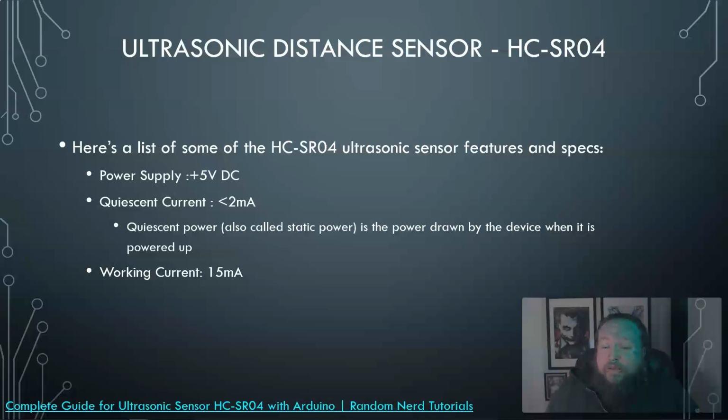But we know this ultrasonic is going to take that. So if we threw in 2 ultrasonics, if we're even able to connect that to our controller and use that, that's going to be a total of roughly 15 milliamps drawing, and that's more power consumption. Even just having 2 sensors, throw in some actual effectors and actuators there, it's going to draw more power and could cause issues. You're up to that max of how much power the Arduino can provide. And if it's plugged in by USB, well, you've got limits. If this is by battery, that's also going to affect how long the battery source you're using is going to last. But you need to look it up.